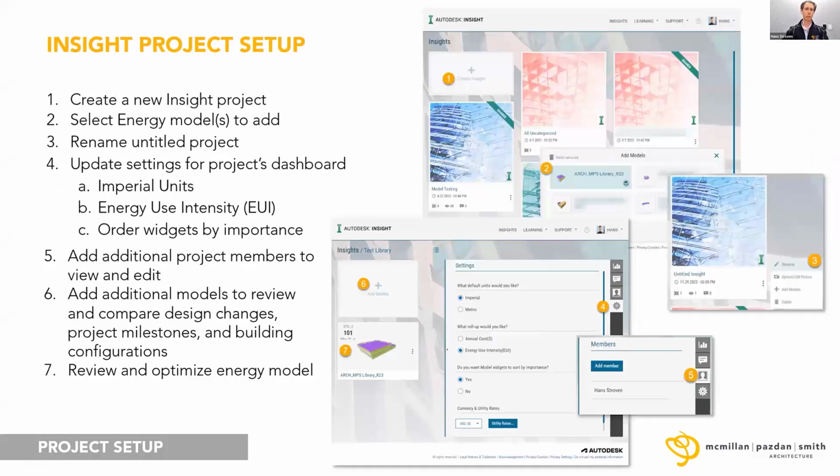So part of this too is once you push your model up to Insight for the very first time, you'll need to go ahead and set up your project. I'm not going to go through every step in here, but I do want to note, depending upon which country you're doing this out of, to set your units. By default, it's set to metric. So if you're operating out of the US, you'll want to set that to imperial units. And then also setting that energy use intensity, switching that over to your EUI.